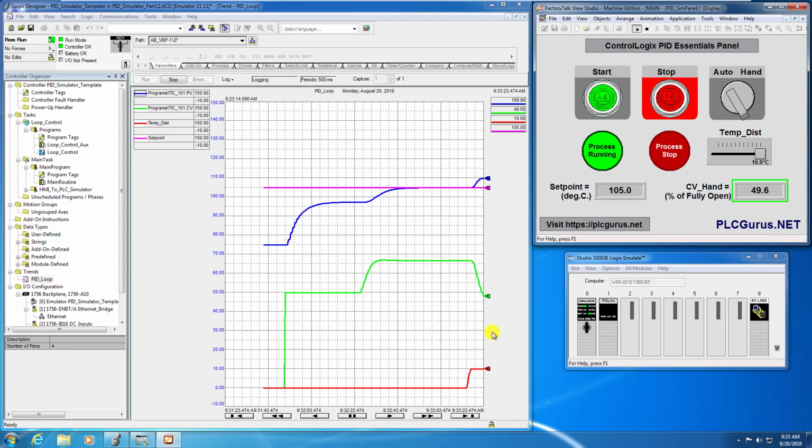And notice now we're adding heat energy in from an external source. So our valve is closing. We don't need as much steam now in order to maintain set point. And you can see there we had a little bit of overshoot, but that dead time and lag time is really having an impact now, isn't it? You see that overshoot, and now we're slowly getting there, but we still have stability. We are still able to recover from an excessive dead time and lag time in our process.